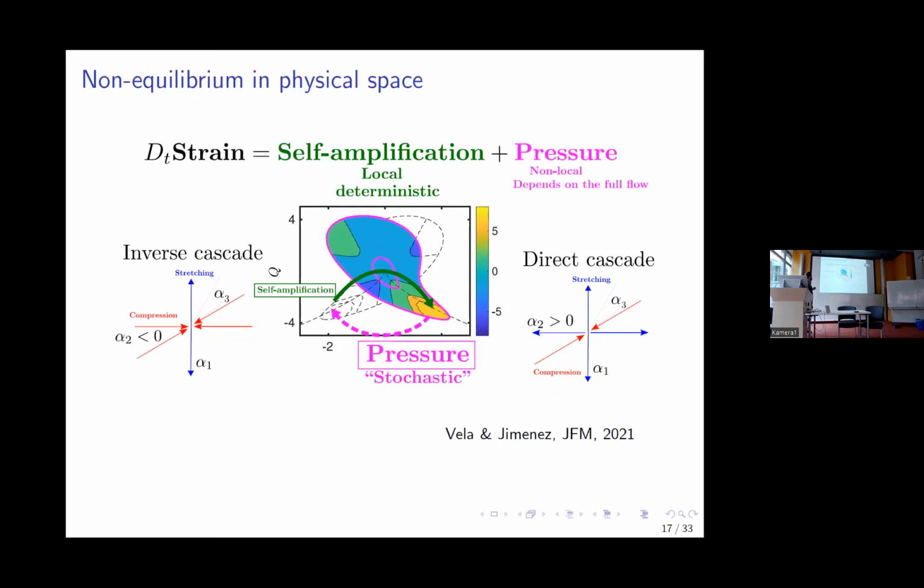And so the conclusion seems to be that if you want to understand why the system goes one direction and doesn't go the other, vorticity might not be a very good indicator. You have to look at the rate of strain tensor, and then you can go to the Navier-Stokes equation. You can calculate the evolution equation for the rate of strain tensor, and try to find out why the rate of strain tensor is generating this type of topology, but not that type of topology.